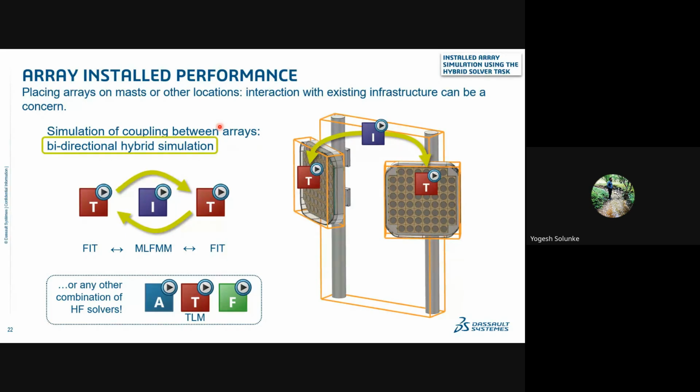Those who want to work or are working on TX and RX antennas, both in a single environment, you can do it with the help of CST. There is a very good amount of coupling between your time domain to integral equation and coming back also. So this comes under the bidirectional hybrid simulation task. With the help of that, big structures, which cannot be simulated using the general purpose solver, can be handled. CST has dedicated solvers like the integral equation and asymptotic solvers.